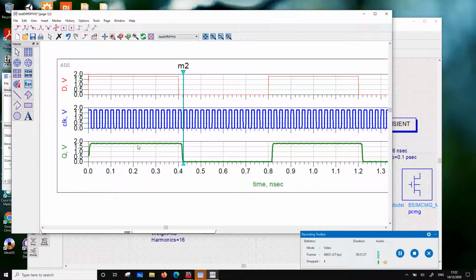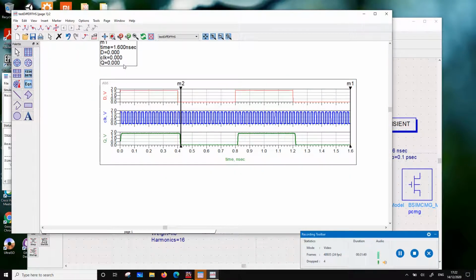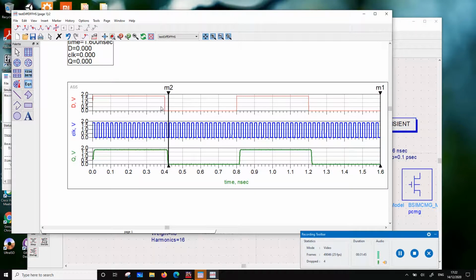So this can be used at 40 gigahertz in a system, but again you have to see in a system what the critical path delays are, and they should not go beyond a quarter of the clock. Okay, so that's how your rough clocking would be done, roughly. Okay, so we are done with this.